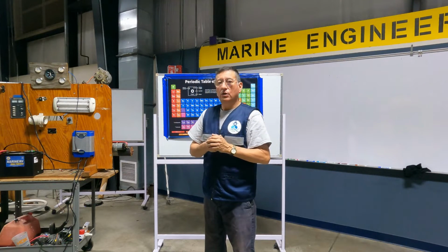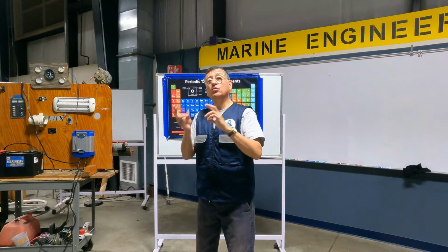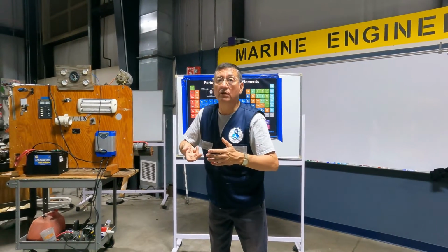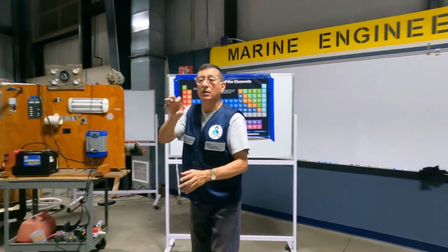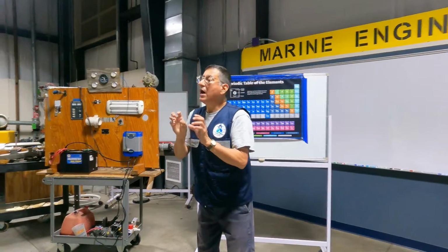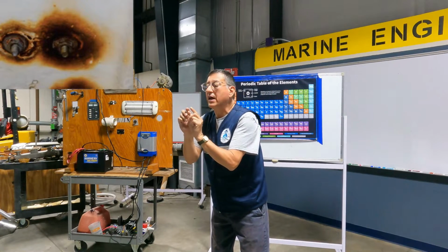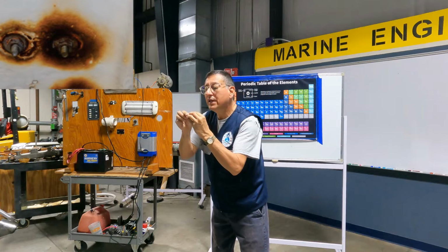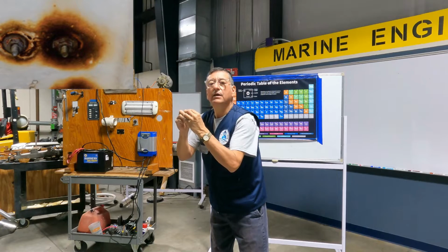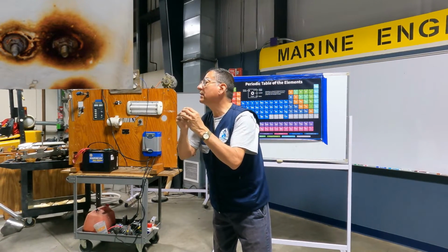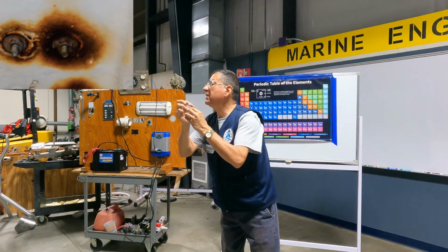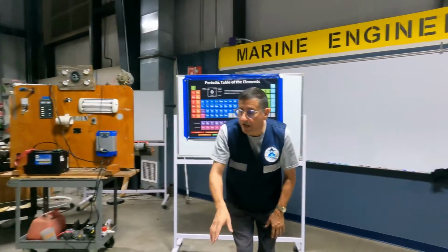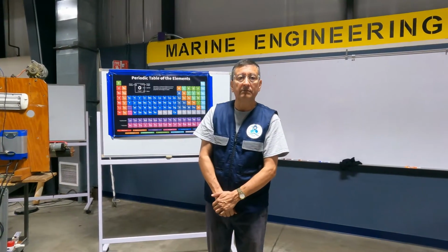3 or 4, no? What happens when you have 2 dissimilar metals in a marine environment? The more noble attacks the less noble. The less noble releases the electrons, and the more noble attracts. What happens in that boundary, in that area around the more noble and the less noble? That area will be eroded. What happens in 2 months with that area? It's attacked by corrosion and is perforated. And wow, the bottom of my refrigerator is completely eroded in 3 months.